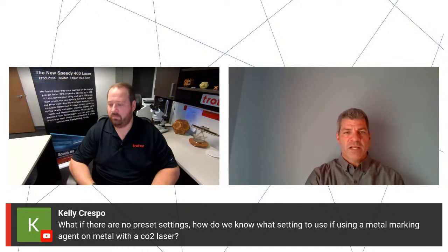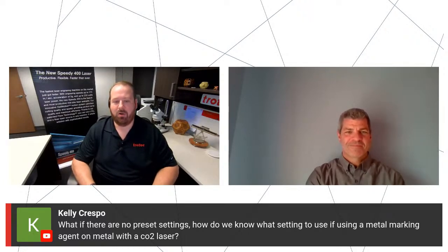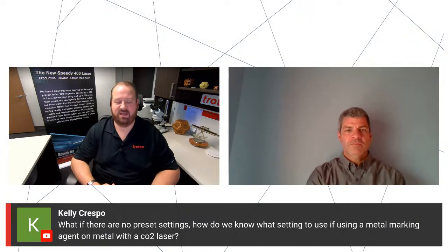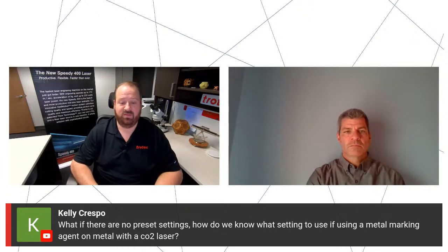In the Galvo software, there are templates included, parameter finder templates. So on any given material, you can run those templates and it gives you the range of possibilities with different frequency, speed, and power. Oh, that's great to know. It's funny, I don't think I've ever really had to use that one. I've always dialed it in manually. So yeah, there are resources for you on the flatbed. Like I said, watch the video. And as Andy just said, there's a preset if you have a Galvo system, to use the built-in features to dial in those settings. All right, next question.